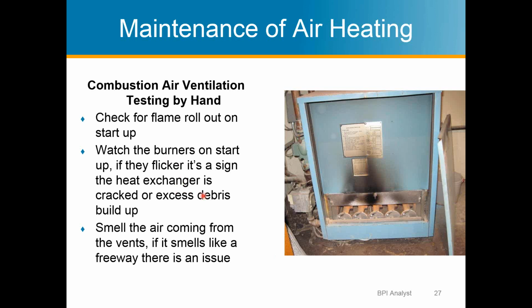The blower motor that moves air inside the house should never come in contact with the air inside the heat exchanger. But the way these turn on is the burners kick on and run for maybe 10 seconds before the big blower turns on and moves air around the house. So for those 10 seconds, you'll have a steady flame.